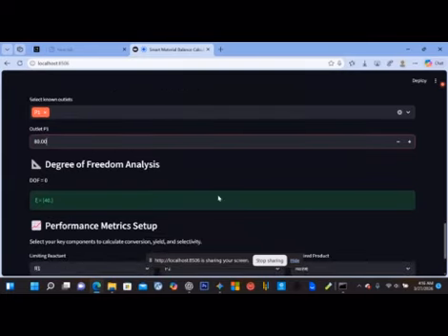Also, the Smart Material Balance Calculator has this feature of performing the degree of freedom analysis for us. When it performs the degree of freedom analysis, it gives us zero. And the degree of freedom being zero means our problem is solvable. It also gives us the extent of reaction, which is the Z, to be 40.